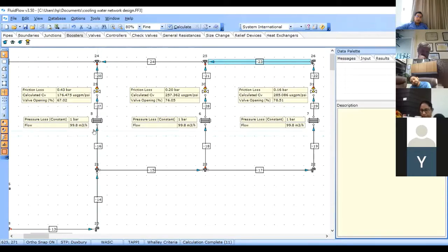So if the water is going in the shell side or the tube side, there is a chance that the shell side or tube side will not have full liquid, meaning the tubes will not be filled with the fluid. There could be chances of overheating or some hotspot might get generated. Because of that, we'll always keep it on the downstream, so that even if the upstream system gets throttled, that exchanger will always be filled with our liquid. That makes sense? Yes, sir.